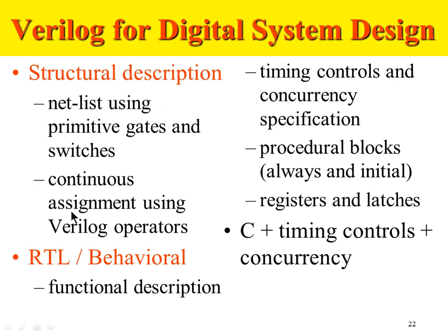One of the things you can do in Verilog is use continuous assignments, and using those continuous assignments, you can build a netlist of primitive gates or switches which are interconnected with each other. It's like a schematic design basically. A schematic always consists of a netlist, and the structural design consists of a netlist.